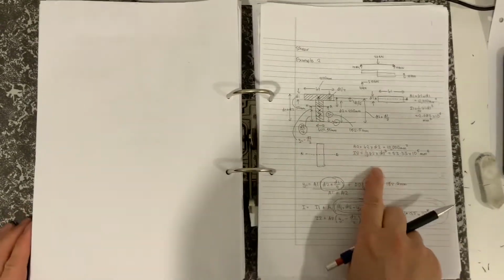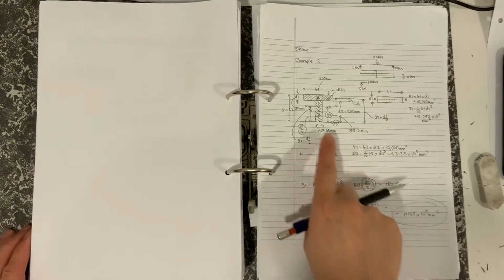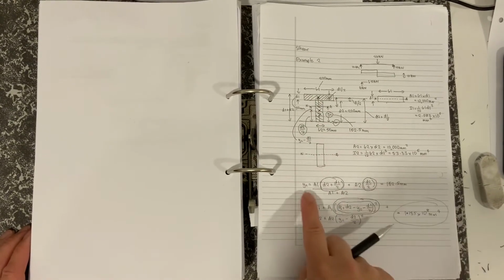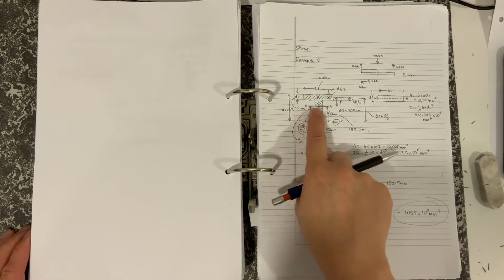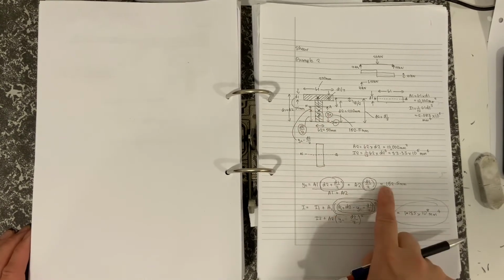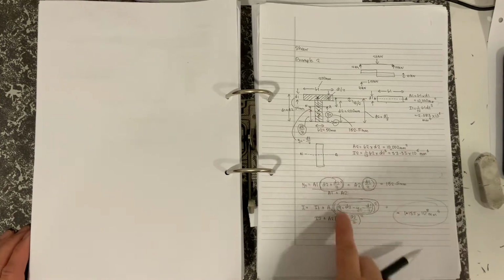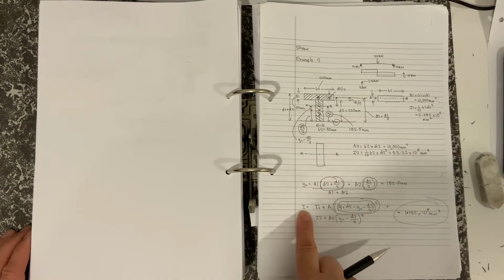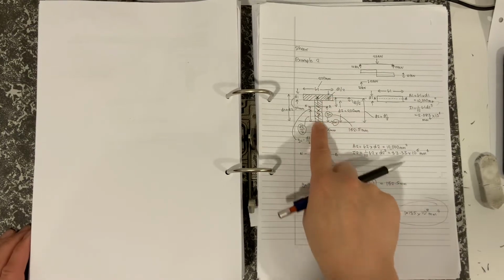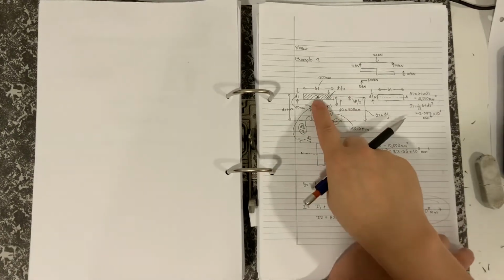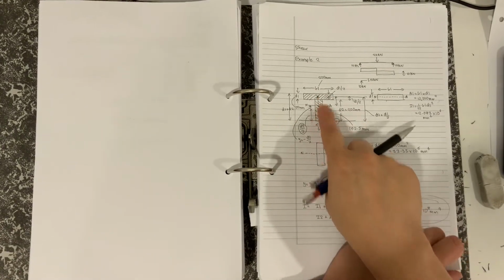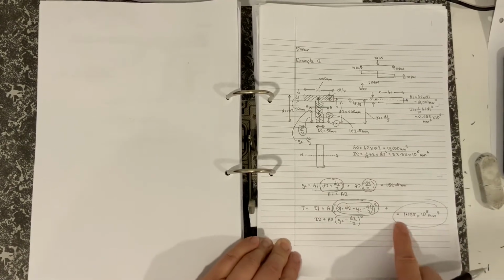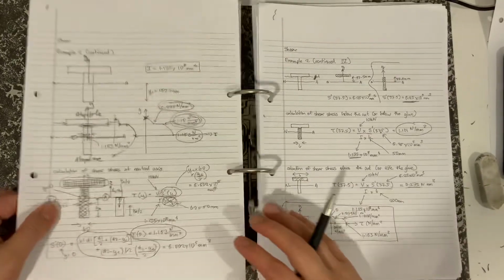So the first step would be to work out your area 1 and your area 2, work out the second moment of inertias, and then find the position of the neutral axis, as we just described. And then once we've got the neutral axis, then we can work out the I of the combined section, assuming of course that the glue is strong enough to stop the two sections from separating, which we assume that it is. And so I've got a value of I.